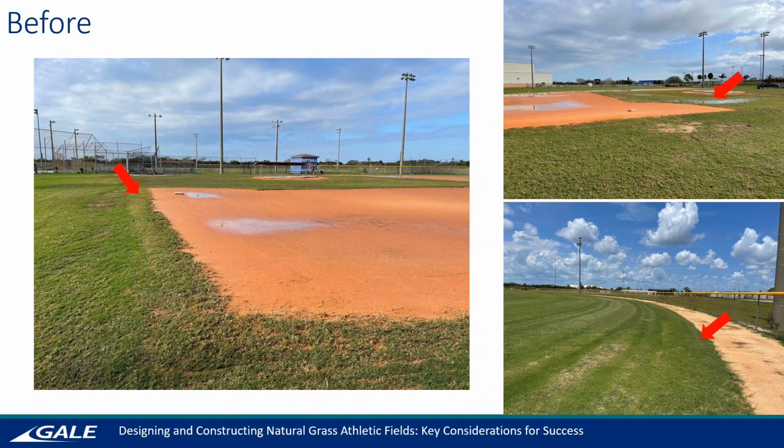And then some of the other issues here is when you got to the outfield, there was again like a hump, like a large lip between when it transitioned from the outfield into the warning track, and over time that warning track had reduced in size. It was getting close to about 6 feet now, where originally it was at the recommended 15 feet warning track length. So there were issues there that they needed to take care of.